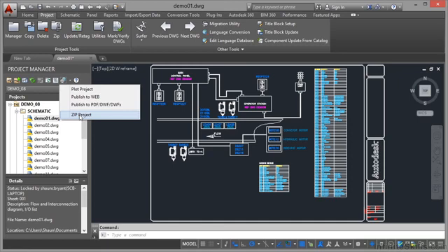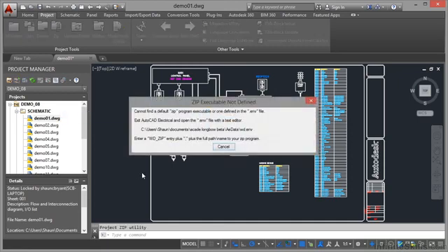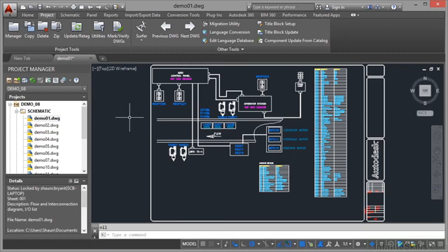Last but not least, we've got the zip project option. So if I click on that, I'll get an error. And I know I'll get an error because I haven't set up a default zip program executable. When I zip things up, I normally use something like WinZip, for example. And then you can zip all of those up, but I haven't actually told AutoCAD Electrical where to find that WinZip executable. And that goes into your .env file for this particular project. You would specify it, and then all you've got to do is put a text editor up on the screen, go to the env file, open it up, and you can edit it. So you can see there that I haven't got a zip executable defined. So I've just got to go and find one, make sure it's in the envelope file, or environment file as it's normally known as well. Envelope or environment, it does vary from company to company, project to project. So that's how you do your batch plotting in lots of different ways in AutoCAD Electrical.